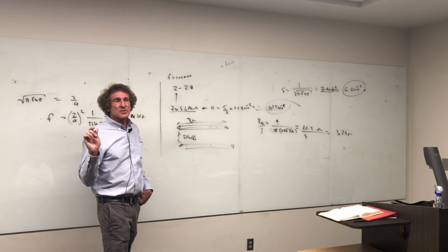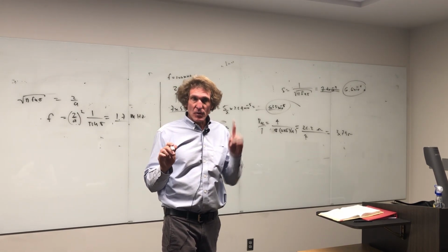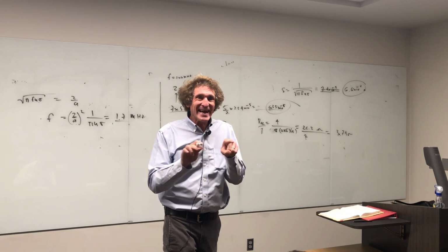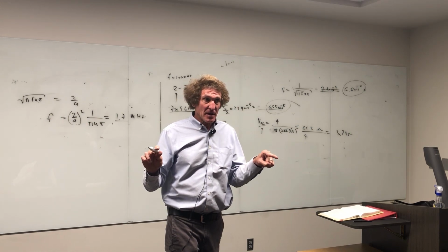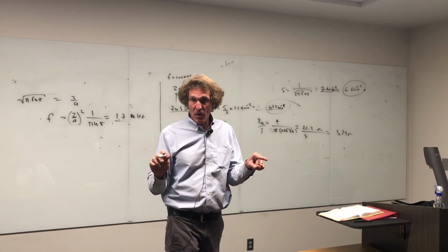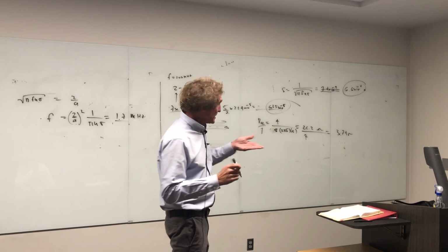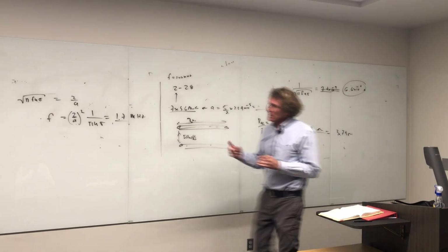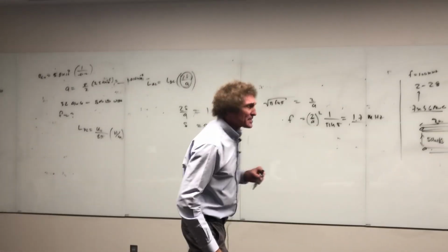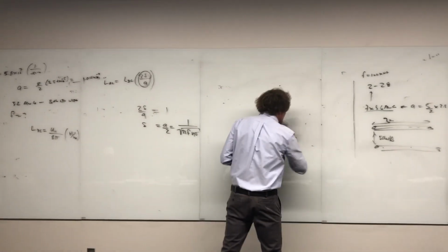All right, now, listen to me. For inductance, this is the thing you have to understand. Once we get the inductance per wire, when you put inductors in parallel, it's divided by the number of inductors. Do you understand that? Now, if there were capacitors in parallel, we'd add them directly. But with inductors in parallel, it reduces the inductance. It's not something that's intuitive, all right? But it is the way it happens. So if we're going to do the inductance one, we can do it right here. The rest of this, the capacitance, is just the capacitance between the 2 lines, and I can show you what that is in a second.